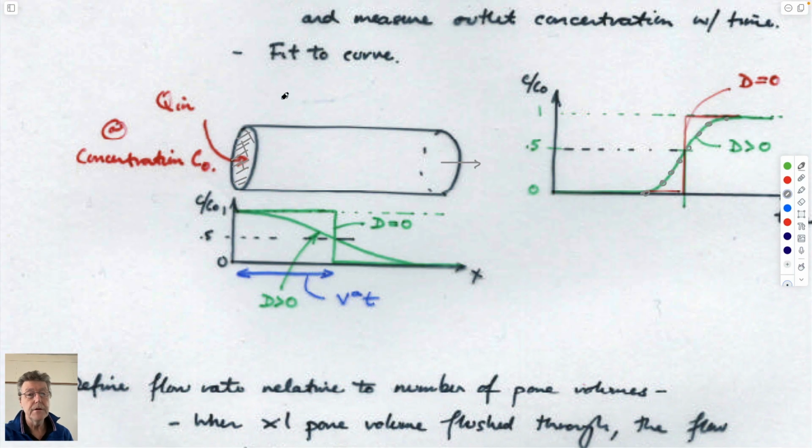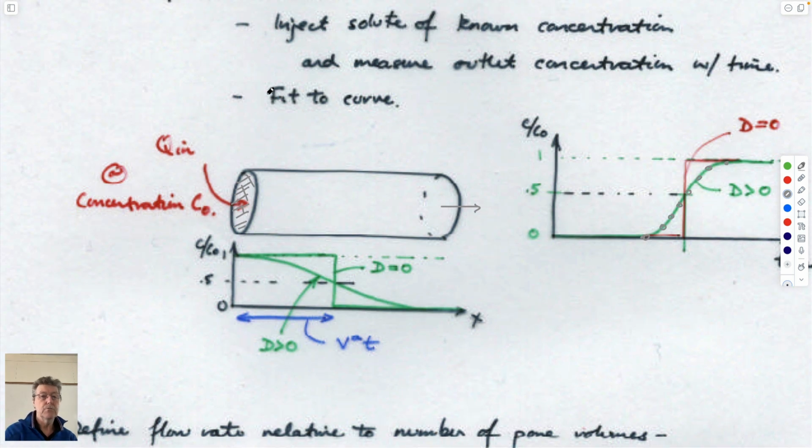And that Peclet number would give you a velocity times a length over D sub L. You know the advective velocity because you're putting water through it, and you know how long your core is because that's where you're measuring the behavior, at the bottom end of it.